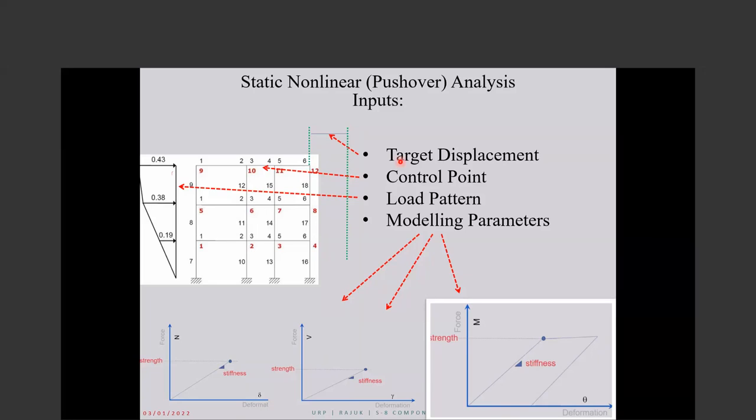So it's numerical. We try changing different software; usually it tries to do its best and reaches the targets. But sometimes it's not a numerical problem. You ask for this building: the demand in this level of earthquake is, for example, 50 centimeters, but the capacity of the building is 5 centimeters. So whatever you push it, it doesn't go more than 5 centimeters. That's one possible result.